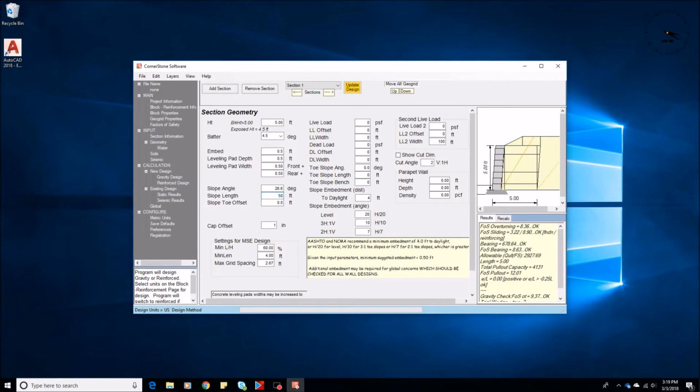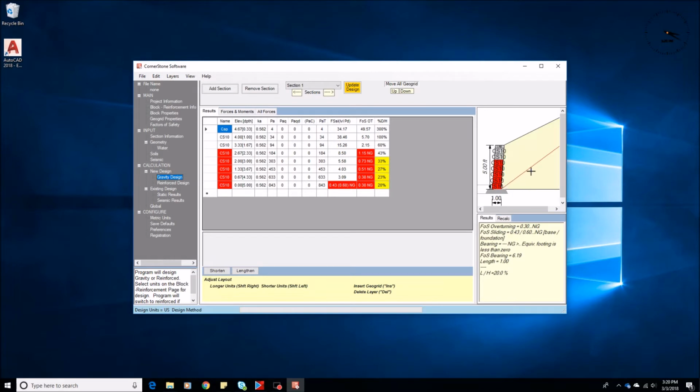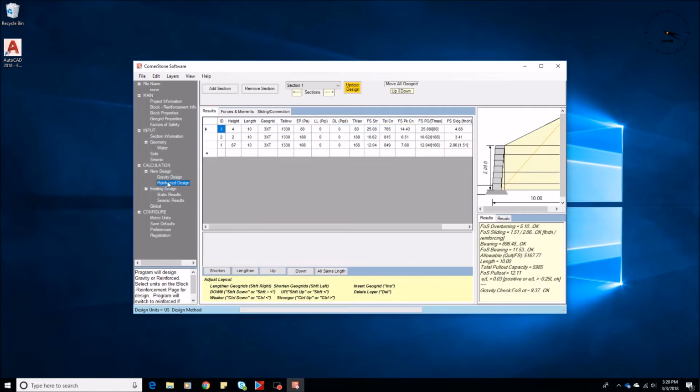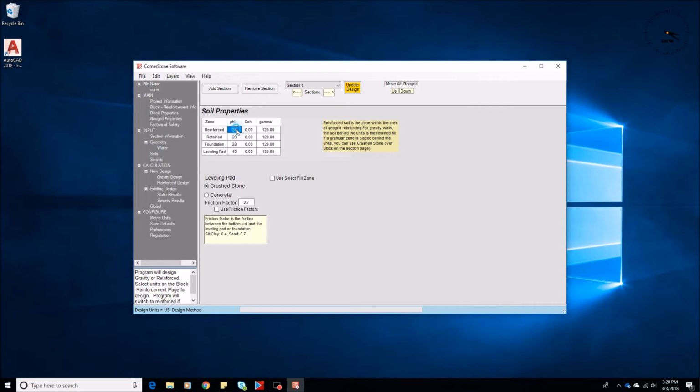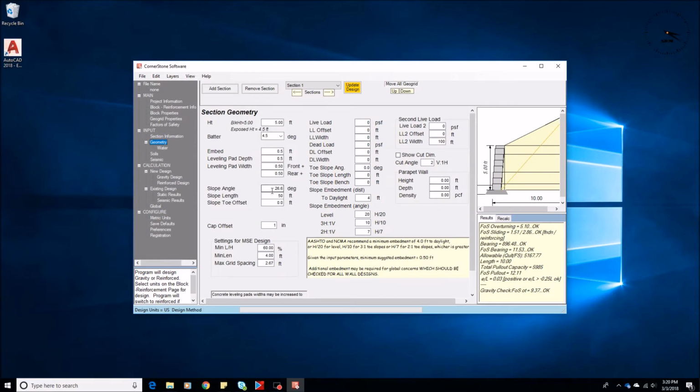We can come in, and if we make that 50, that's an infinite slope, meaning that the failure plane goes beyond the break of the slope, which is interesting in here because the red line over here is your theoretical failure plane. There's your slope angle. When we come back down here and we say that our soils are 28 degrees, our slope angle is 26.6. Those angles are almost together. And if we do an infinite slope analysis, we're going to find that that slope is unstable.